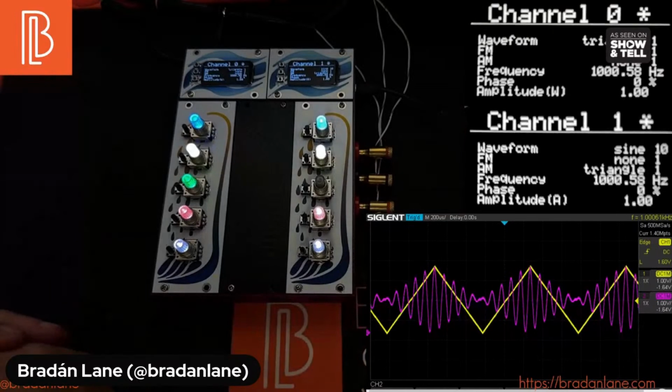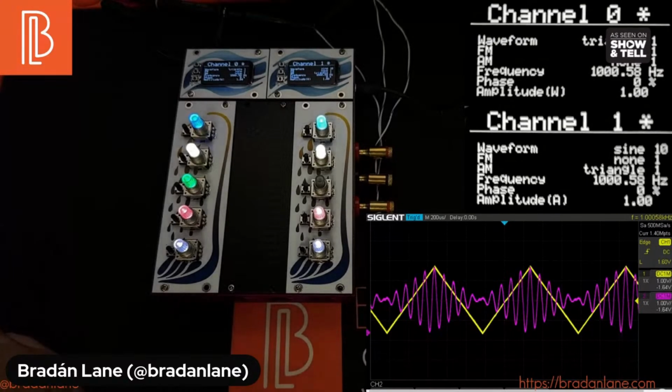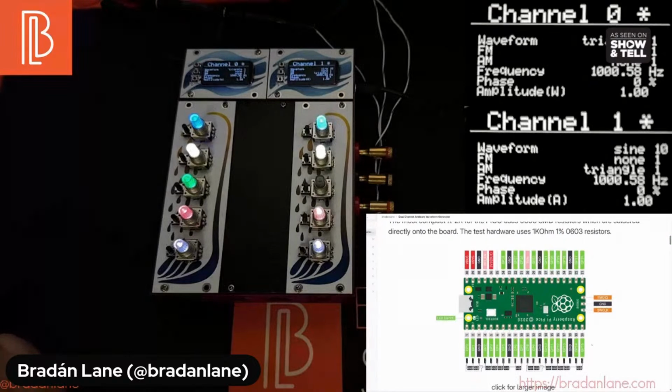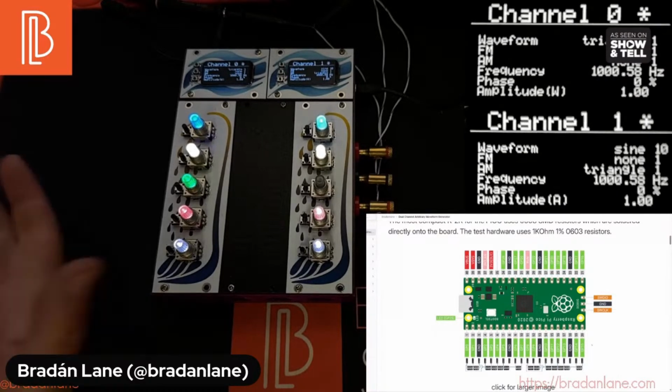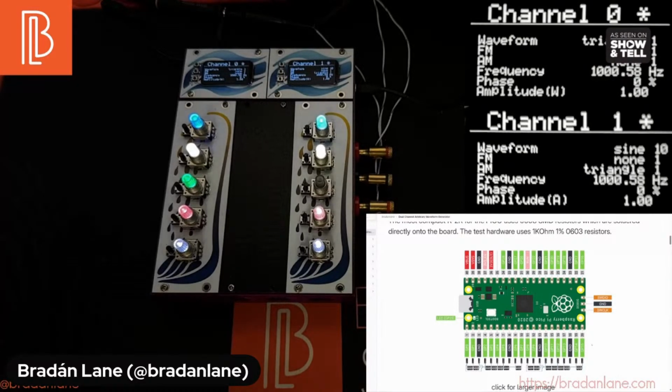And so this is nothing more than a Raspberry Pi Pico and a bunch of MicroPython code. The trick is it uses the DMA. It uses 2 DMA channels linked together. It uses a state machine and it uses PIO. But it's all written in MicroPython. It's all open source. I've published everything out. I use GitHub instead of GitLab, but it's simply called AWG, the number 2, CHAN for arbitrary waveform generator 2-channel.